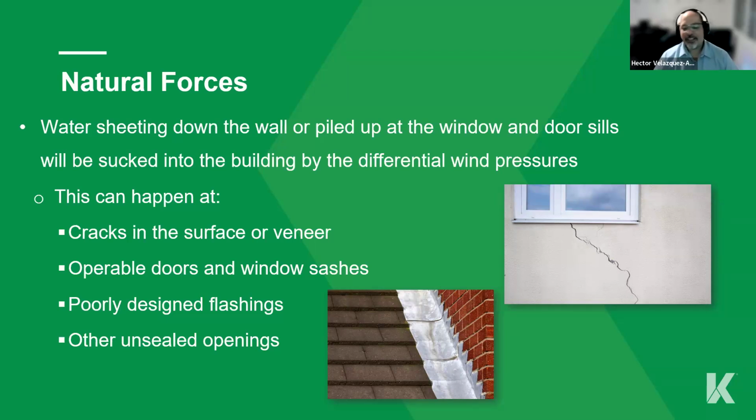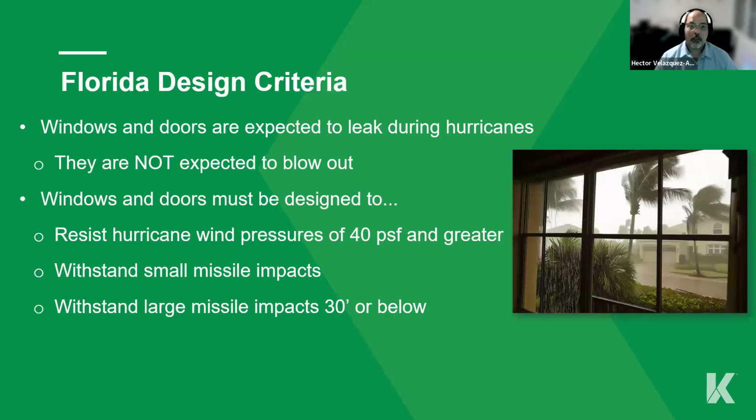Correct. Let's not forget also about the roof. The flashing on the roof is also critical. That's a big major area of water intrusion when it's not performed properly, when it's not maintained properly. That's another big source of water intrusion to your building.